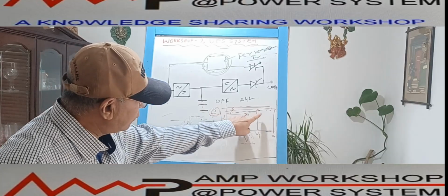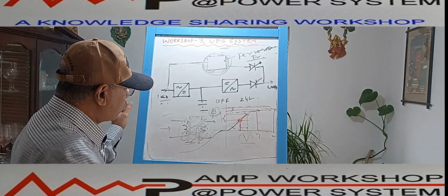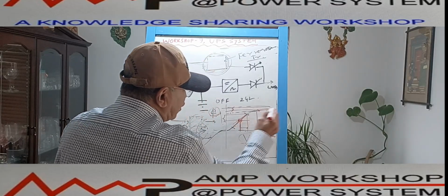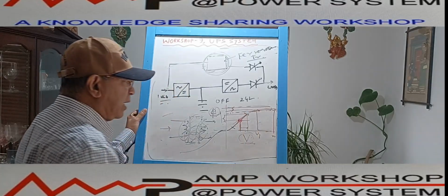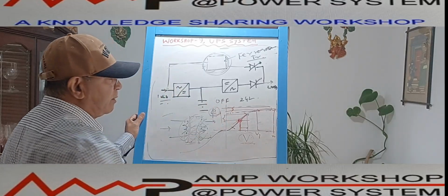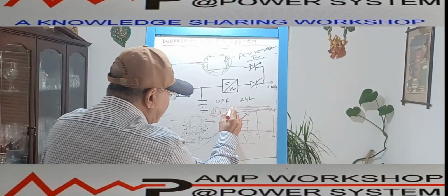So if I use a transformer whose core is designed near the saturation point of the magnetization curve, then what advantage will I get? The input voltage variation will be very wide, but the output voltage variation will be very small, because the flux change is not there.